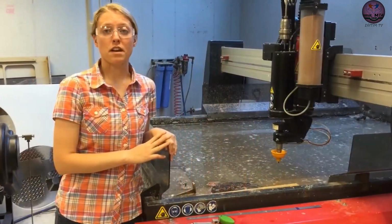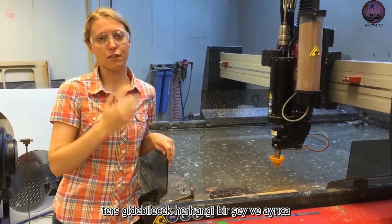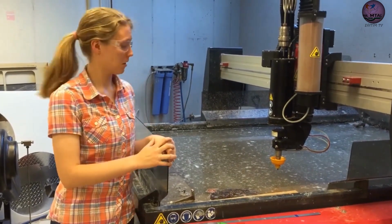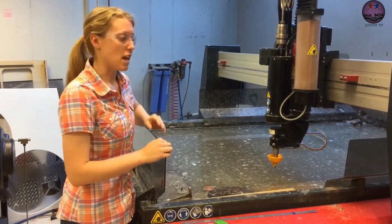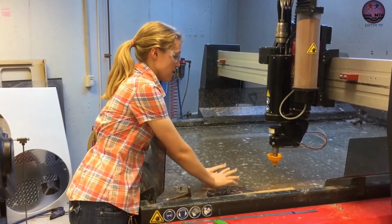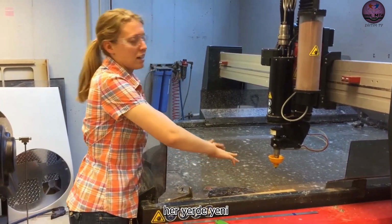When using the water jet, it's important that you always wear safety glasses. This protects your eyes from anything that could go wrong. And also, when the water jet is running, never put your hands inside the tank. It is very high pressure water and you don't want it anywhere near you.